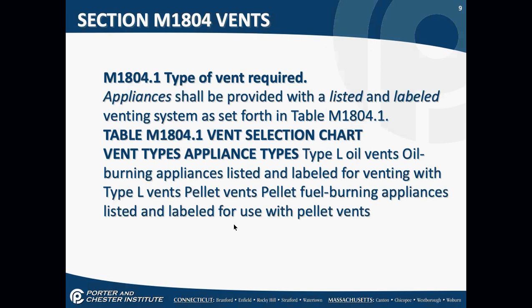Okay? There's a very strictly controlled type of venting required. Appliances shall be provided with a listed and labeled venting system as set forth in Table M, which stands for Mechanical Code 1804.1. Type L oil vents are what oil burning appliances use. Okay? Pellet fuel sometimes has different requirements for venting. Again, it depends on the appliance.